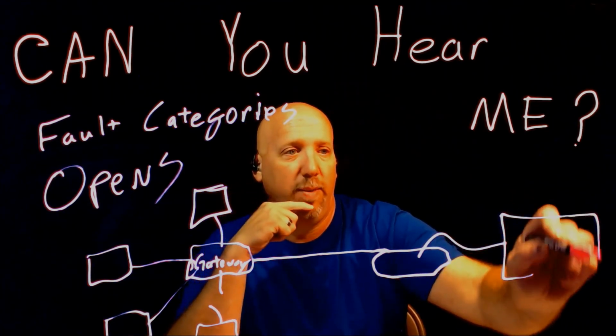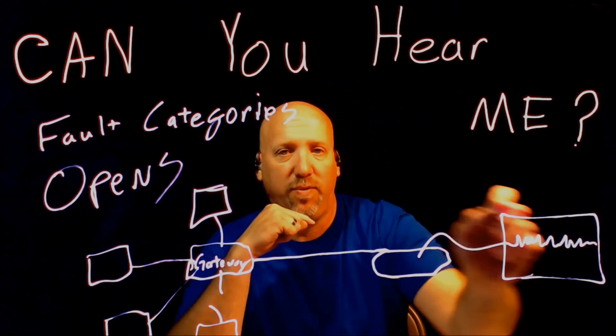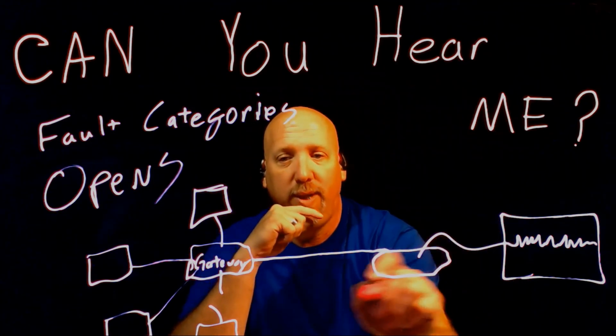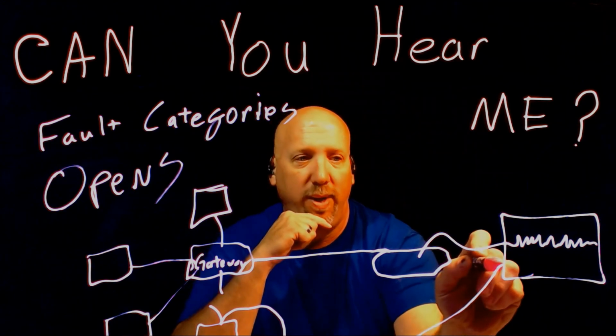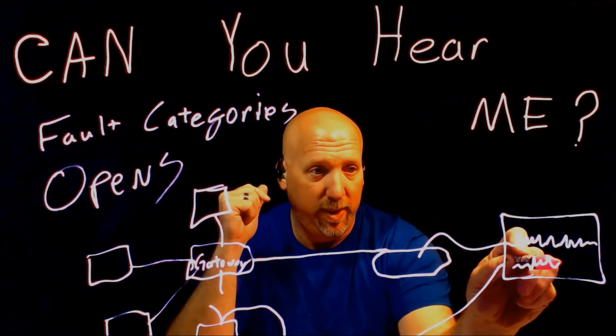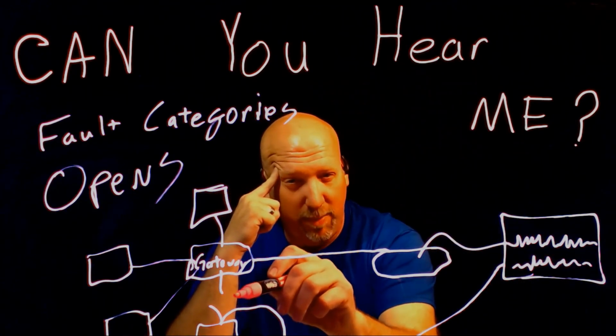And at our lab scope, we're going to find this right here. That's one channel, but it's a two-channel lab scope. The other one we're going to test right here. So our waveform right here will be the same there. Once it's the same, you found your open there. Does that make sense?